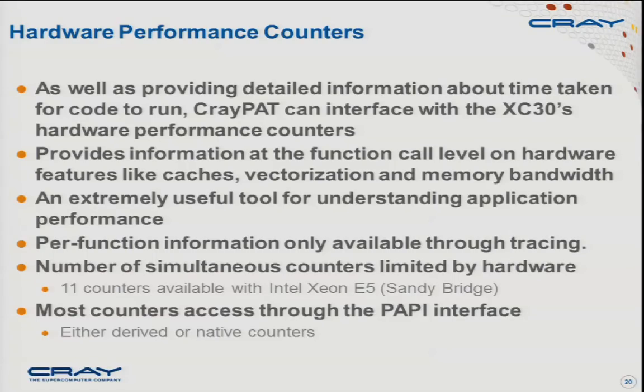So yesterday was this description. Basically, you can imagine there are specific registers inside the CPU. They are called PMU registers, and there is a given number of registers which are fixed. People said, okay, these registers count how many clock cycles and so on, so everybody is interested in this. In the standard bit, there are 3 registers you cannot change. And then there are 8 registers, so in total 11 registers, counters, where you can change the value that you want to register. So they are optional, basically, okay?